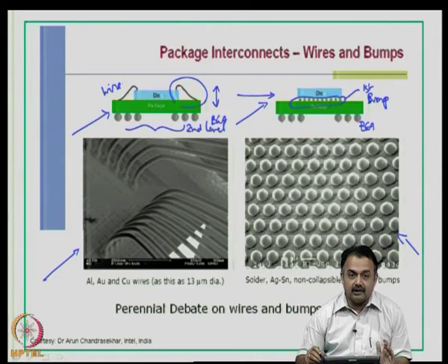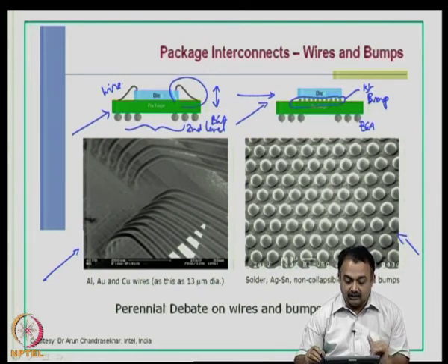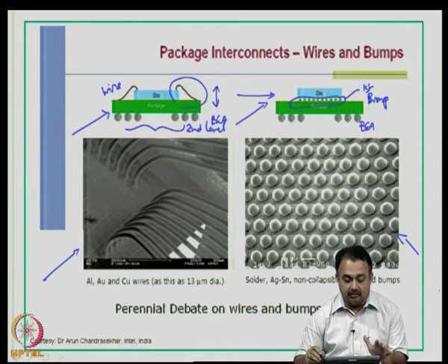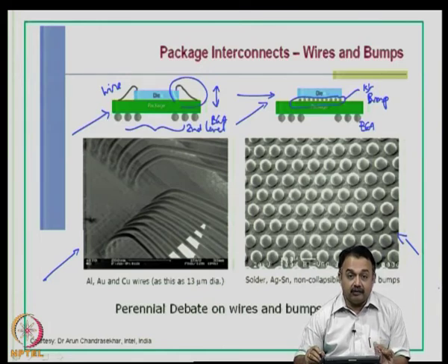We are not going to consider here a wire and a lead frame, because typically that is low dense. These two options that I have presented here in this slide are typically high dense packages, because it is ball grid array which enables you to work at low pitch, but the first level interconnect here are varied. One is a wire, the other is a solder bump.